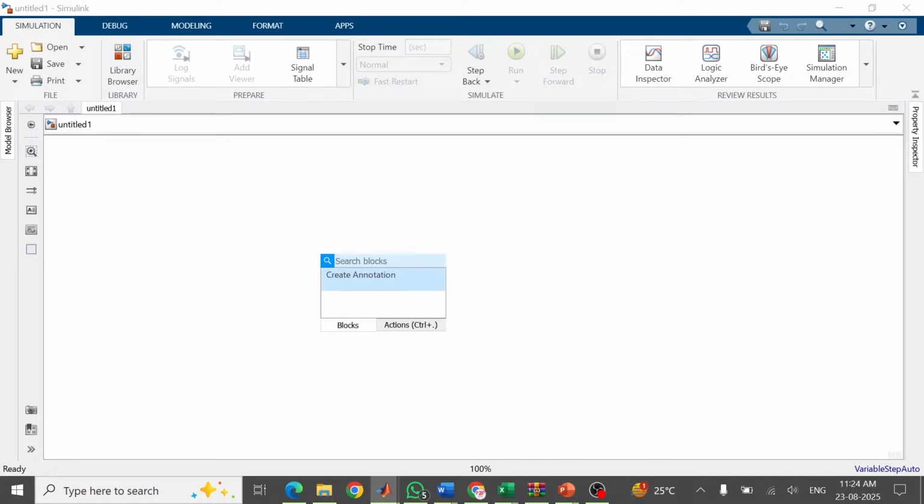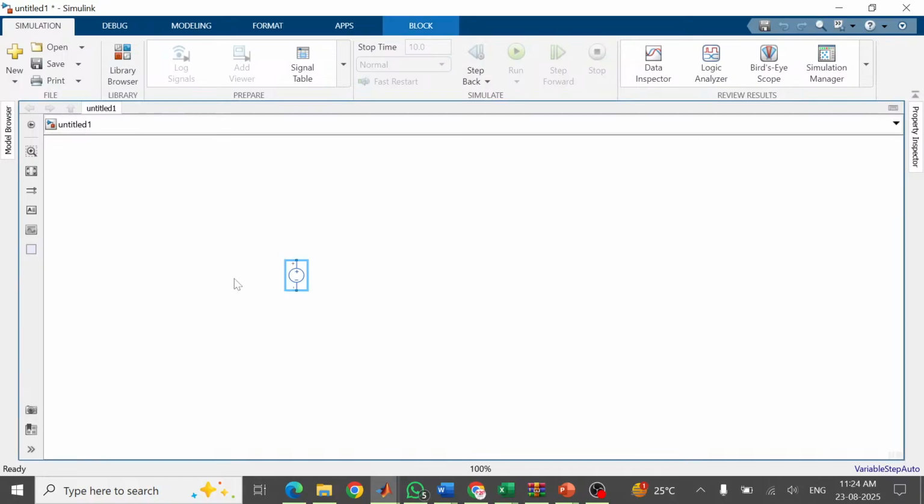Take one DC voltage source. That is one part of the electrical vehicle that we are already designing, just keep it. Finally we can integrate all the components. So take one DC voltage source from Simulink, a Simscape component, like this type of component. Take this block and take one DC machine, the DC motor. You can type DC motor.